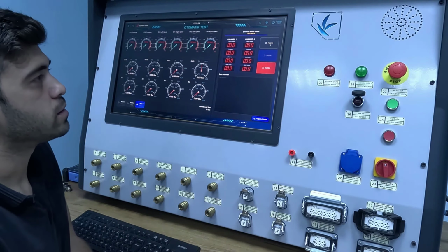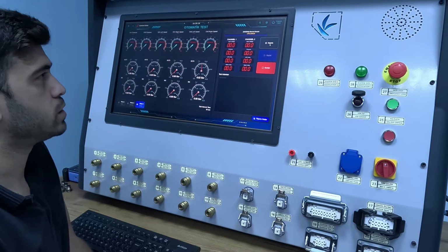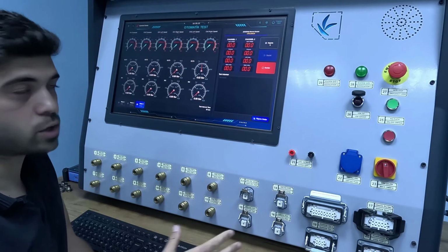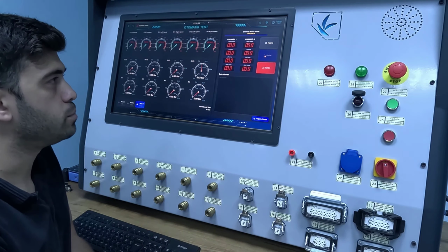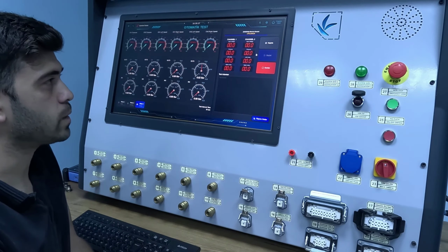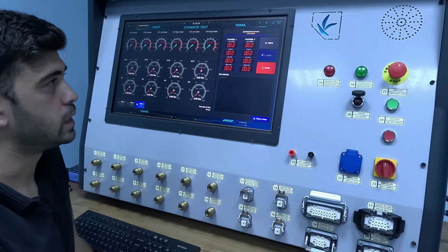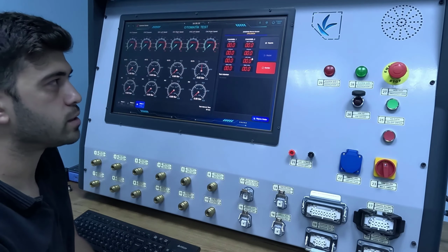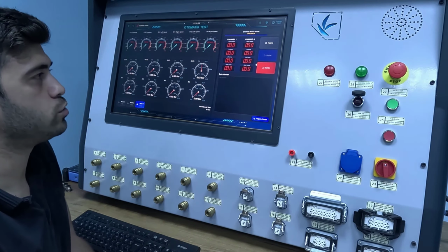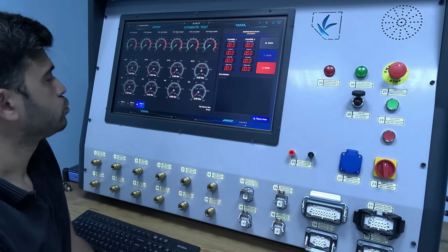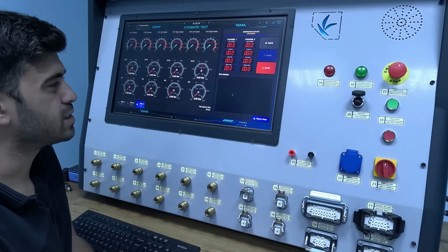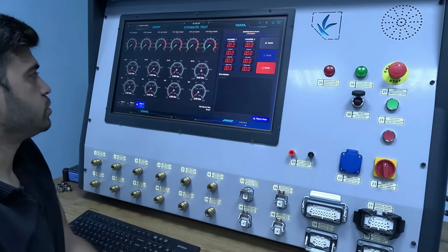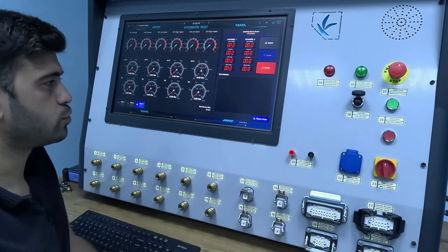Okay, so in the test steps, first when we say prepare, a specific scenario will be applied to EBS. Apparently, the scenario is being sent by computer to the brains inside the HVD, and those brains are applying that scenario to the EBS. When we say start, the scenario application begins, certain pressures start being applied to the EBS. After that, you can see the scenario step by step in the test steps section here.